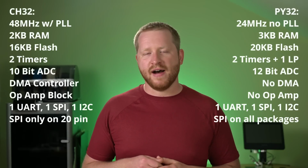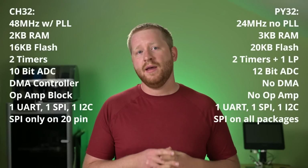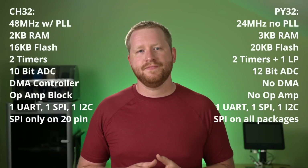They can both operate at 5 volts, they both have comparable package options and number of I/O, and they have similar low power modes. As you can probably see, it is hard to declare one of these better than the other without knowing your exact application. On one hand, the CH32 is faster and has DMA and that built-in op-amp, but the PY32 has more flash and RAM and a higher resolution ADC.